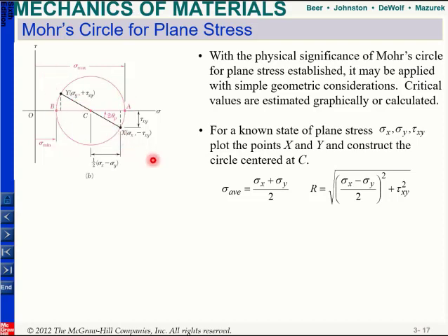After you draw this circle, whenever you rotate your stresses on this plane stress condition between the axes x and y, you will just move through this circle. If you look at this graph and I ask you what your maximum normal stress is, you can see that it is at A. This means that if I want to rotate my axis system from xy to this axis system, I need to rotate this line by 2 theta p.